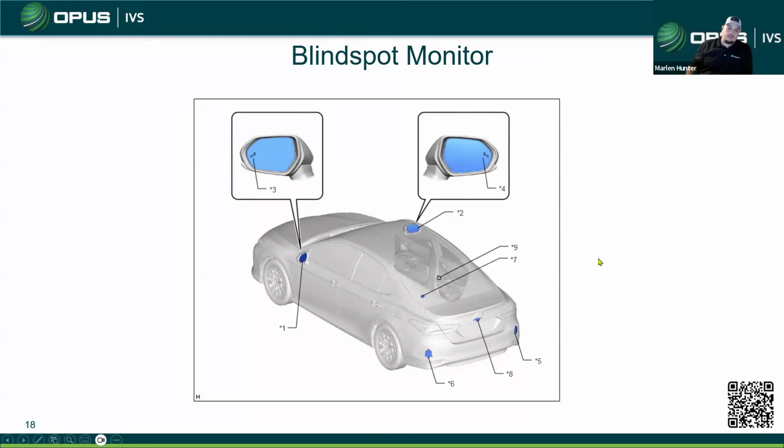Where you run into the biggest problems that I run into is when these cars have been hit in the quarter panel or hit the bumper or somewhere somewhat structural. It depends on the car. Like Highlanders and stuff like that, they put the blind spot module kind of higher up, more like in the quarter panel, versus where you see a Camry or an Avalon, they'll be kind of down in the bumper. The reason I say these cars have the most problems is structural damage. It doesn't always get put back exactly right.